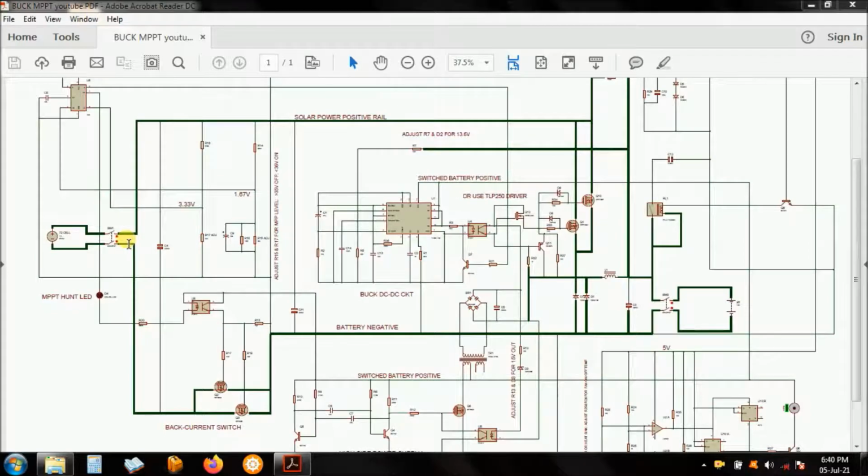The other need for a solar charge controller that uses a power supply, a DC to DC voltage regulator, or a power supply that has transformer isolation, the various types of DC to DC converters, is that you can connect a higher voltage solar module here, charging a lower voltage battery system here. Like these days you have the 72-cell solar modules with output voltage of now 50 volts.